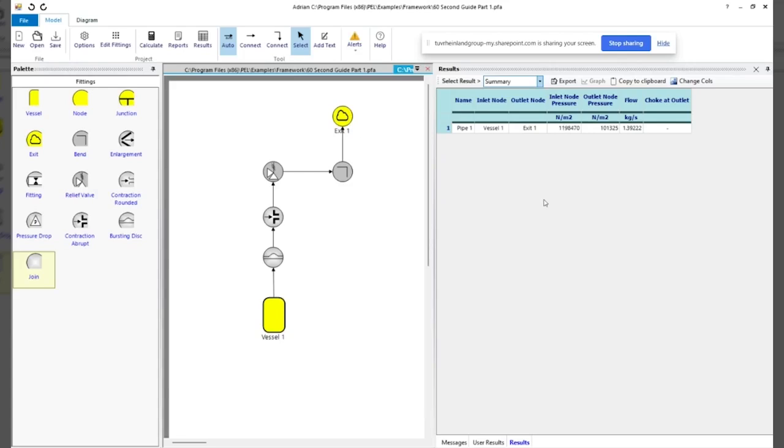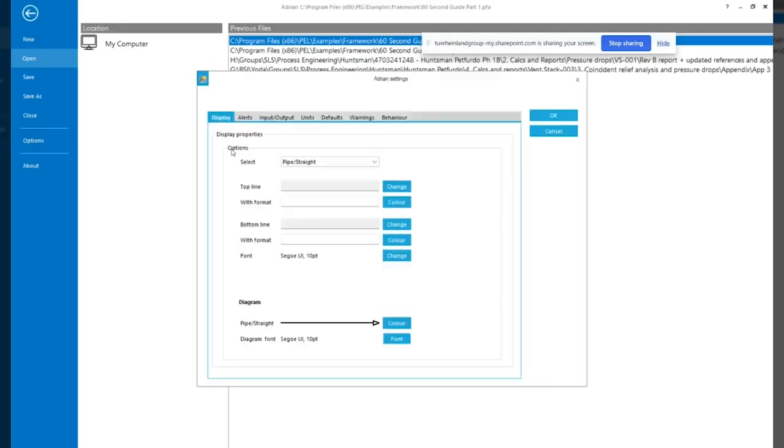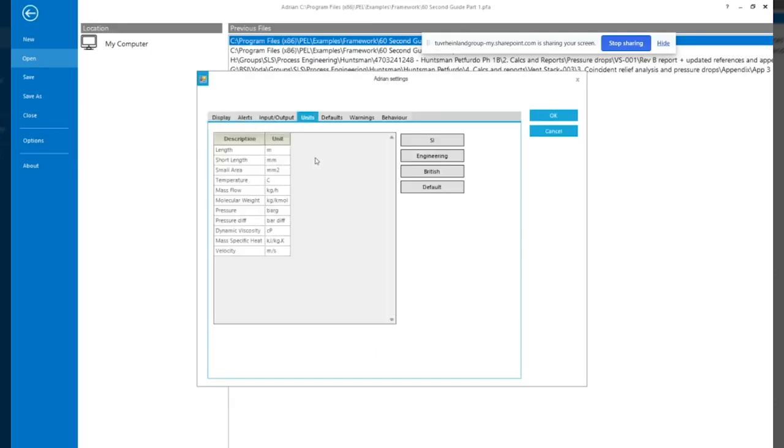So we're now into Pascals absolute. Now I might want, when I create a new model, for everything to default to bar gauge, my preferred set of pressure units. So to change your default set, what you need to do is go over to this side over here, go to the options, and then you get this little box here, very similar. But I'm going to go to engineering.